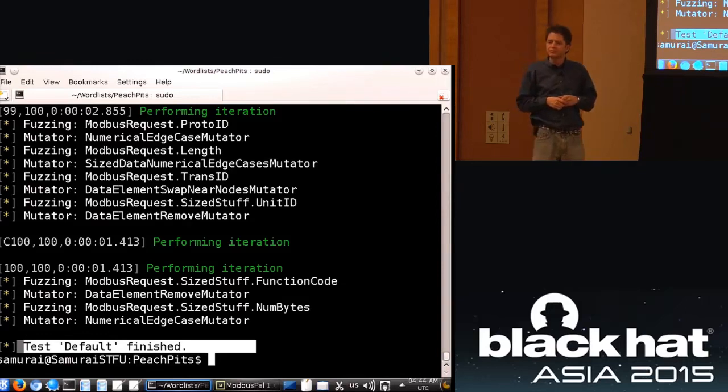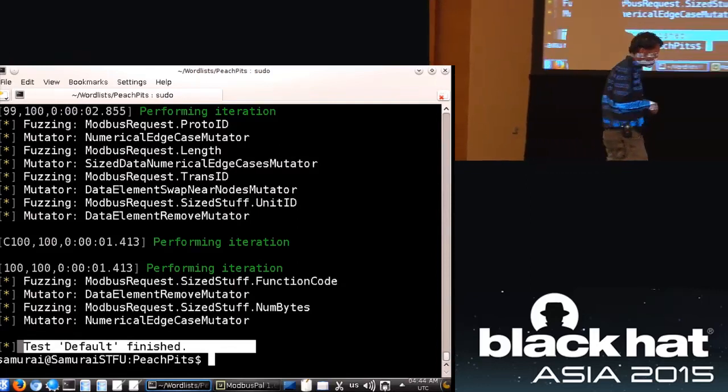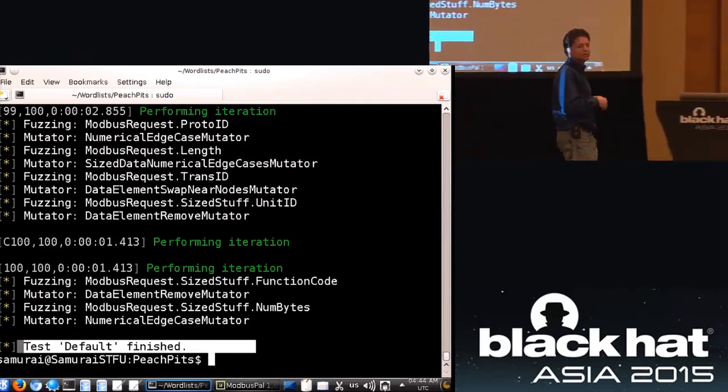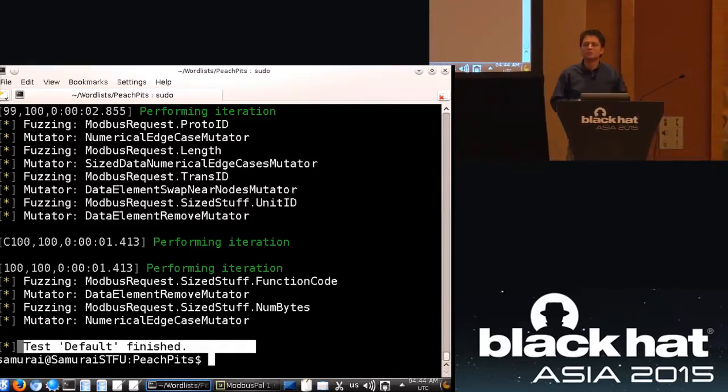For vulnerability scanning tools, yeah, but with port scanning and vulnerability scanning of field devices like PLCs, you have to be very careful. It's not uncommon for you to actually crash them, because the PLCs don't have good capabilities inside of their tools. Okay. Any other questions?